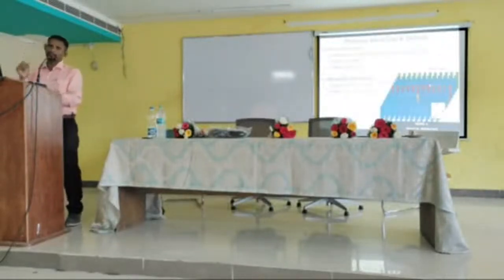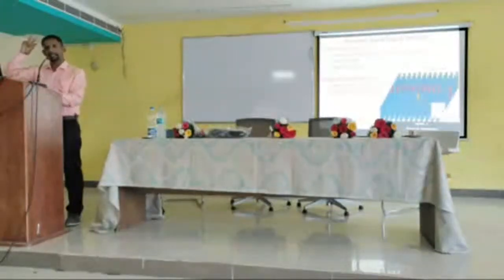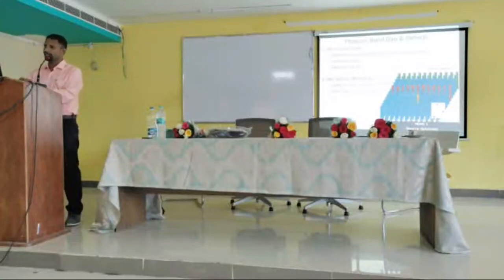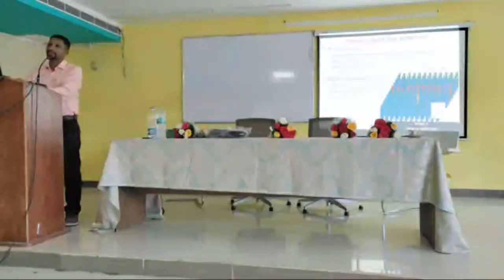So, the photonic band gap depends upon 3 important factors. It is a pillar type structure. First one is dielectric constant or refractive index or permittivity, and second one is the lattice constant, distance between 2 holes or distance between 2 pillars. Third one, radius of the rod or radius of the pillar. Based on the 3 structural parameters, the size of the photonic band gap varies.